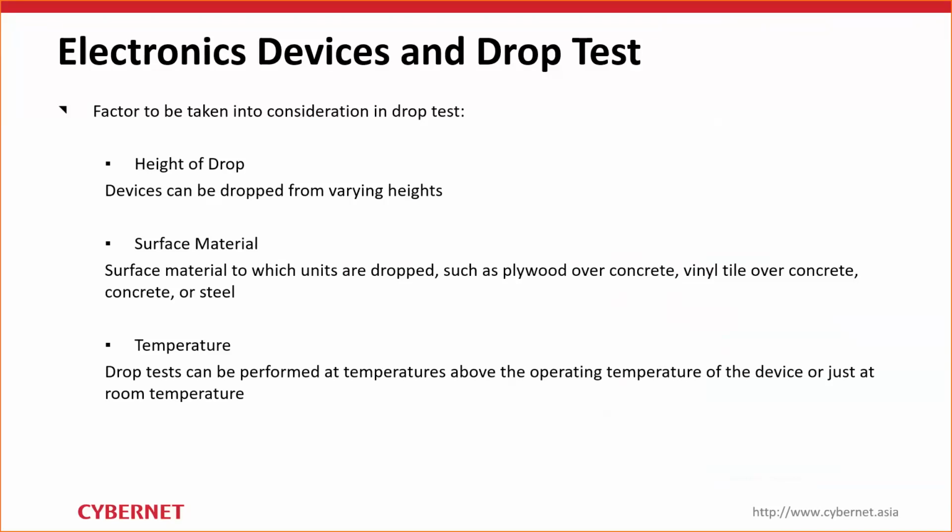Then, of course, the temperature at which drop tests are performed. Drop tests can be performed at a temperature above the operating temperature of the device, or just at room temperature. Again, all of these settings can be incorporated inside the simulation environment very easily. So there is not going to be any problem specifying all of these parameters inside Ansys LS-DYNA.